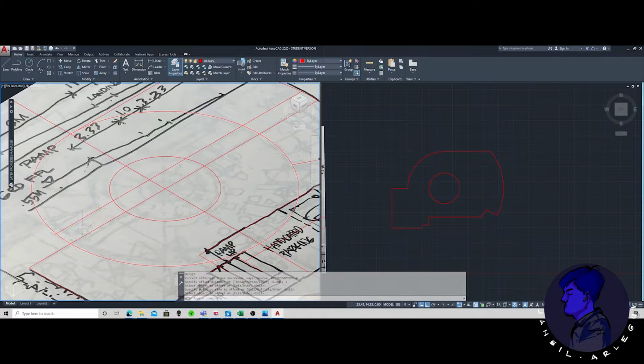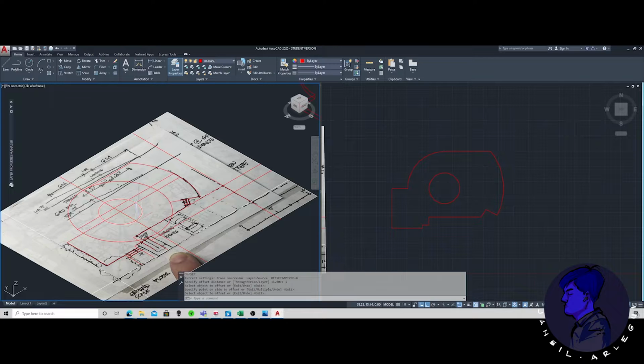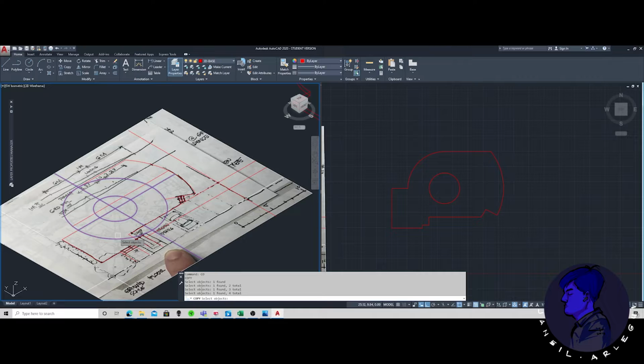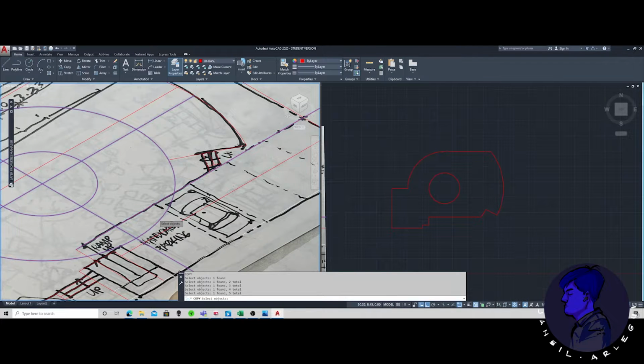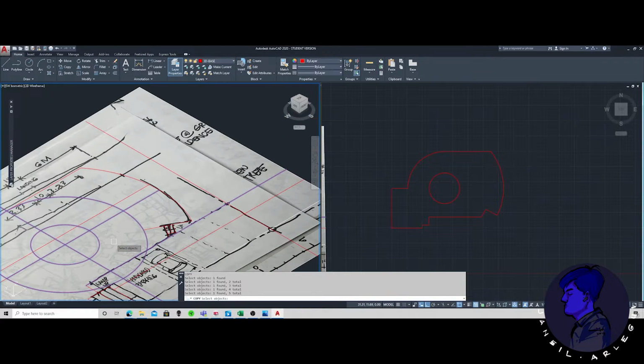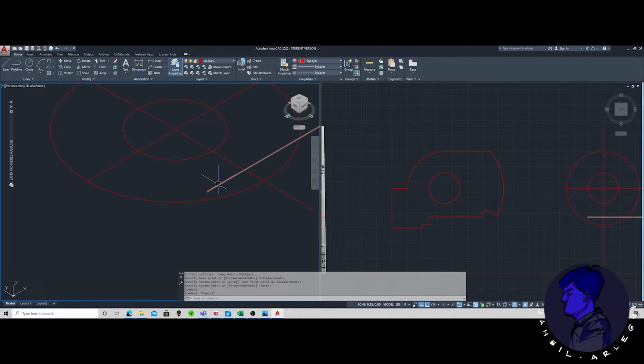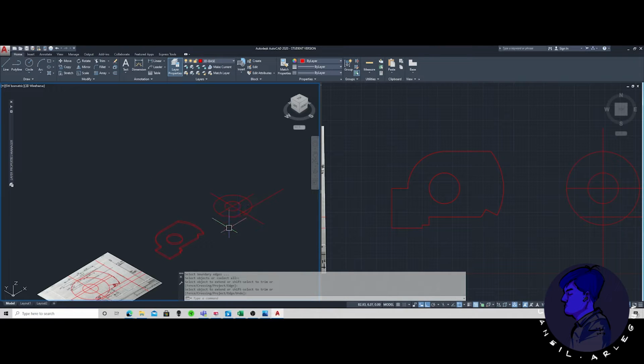And then there's the counter over here. So I'm going to be using this. I'm going to copy, CO, get this center so that I know where the center is. And then the outer curving wall. That line, I need that to extrude later on for my interior space. So I'm going to extend this, EX, going with that. So the outline of what I'm trying to do is this space. This is my target area.